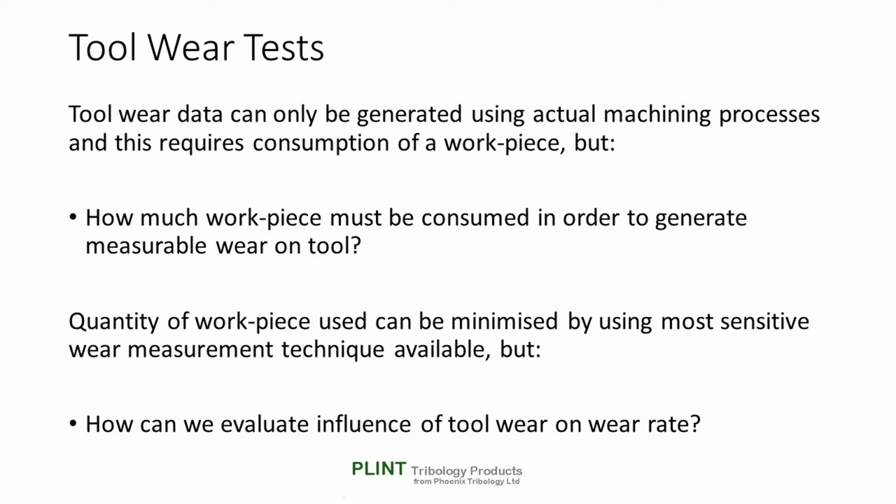The only way to minimize the quantity of workpiece used is to use the most sensitive wear measurement technique available, which effectively means surface layer activation. In this case, the technique is to use an irradiated tool and measure the transfer of radioactive material to the machine debris, the chips and swarf, etc.